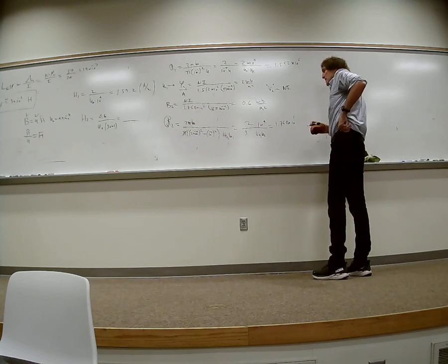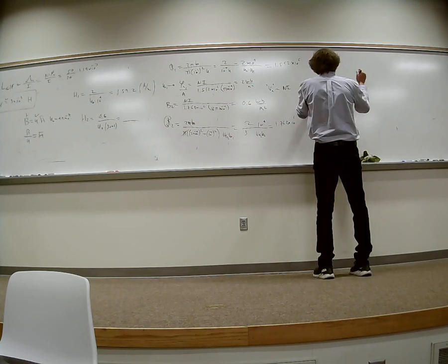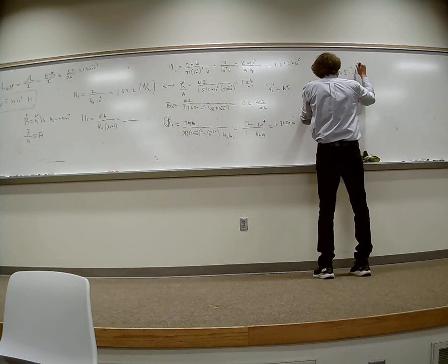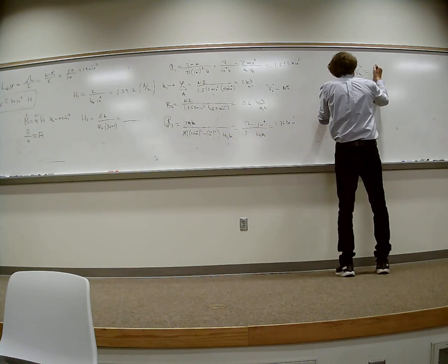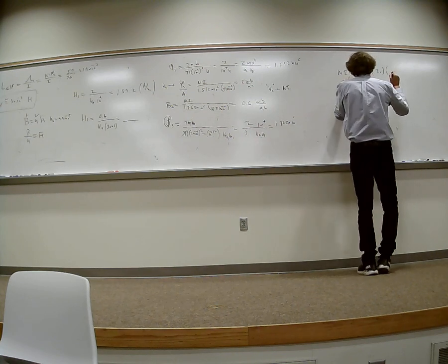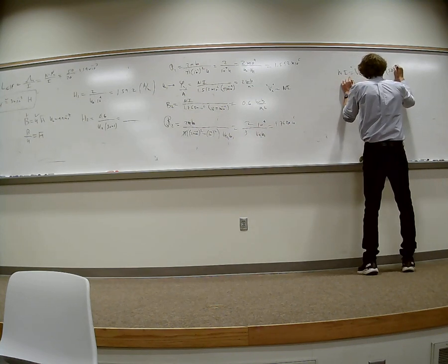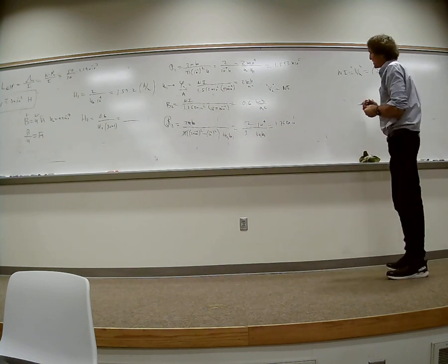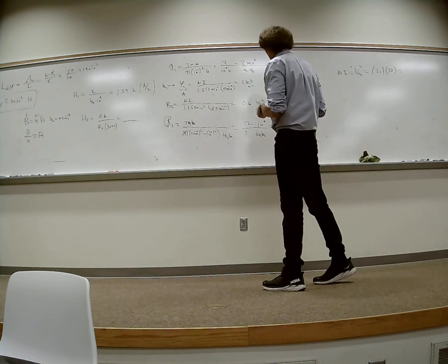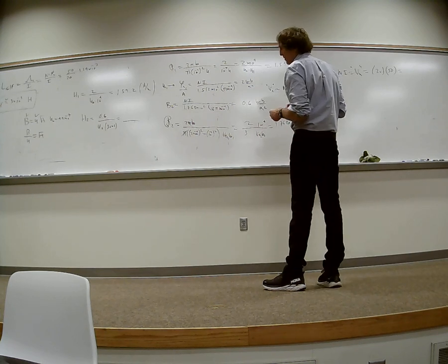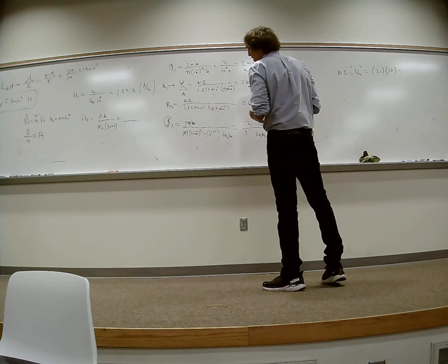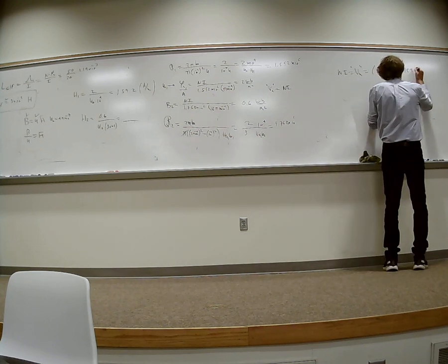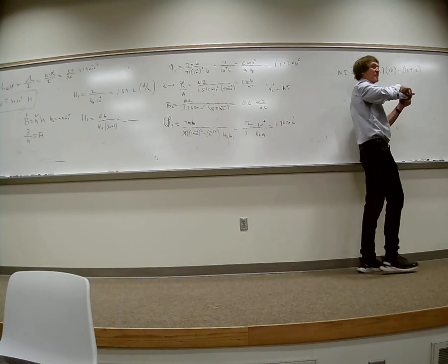Think about this for a second. I have Ni as the magnetic voltage, if you will, and that's 20 times, I guess, 50, or 50 times 20, and that is equal to the H field times the length. We have an H field of 159.2. Yeah, sorry, 159.2.